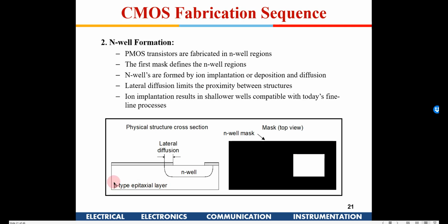So you have an epitaxial layer out here. First you put a silicon dioxide layer, then you put the photoresist for lithography, then you use this mask, and you clear that photoresist, and after clearing the photoresist you remove the silicon dioxide. This is not the N-well for only one PMOS; this is the entire well for several PMOS of your entire chip.